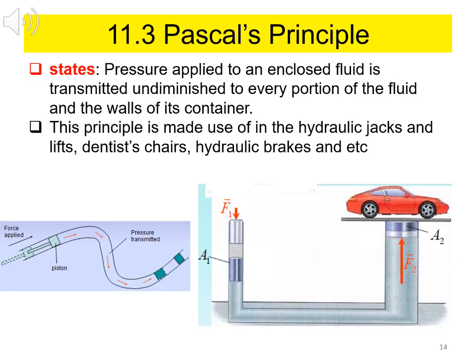Now we will learn about Pascal's principle. Pascal's principle states that pressure applied to an enclosed fluid is transmitted undiminished to every portion of the fluid and the walls of its container. This principle is made use of in hydraulic jacks and lifts, dentists' chairs and hydraulic brakes.